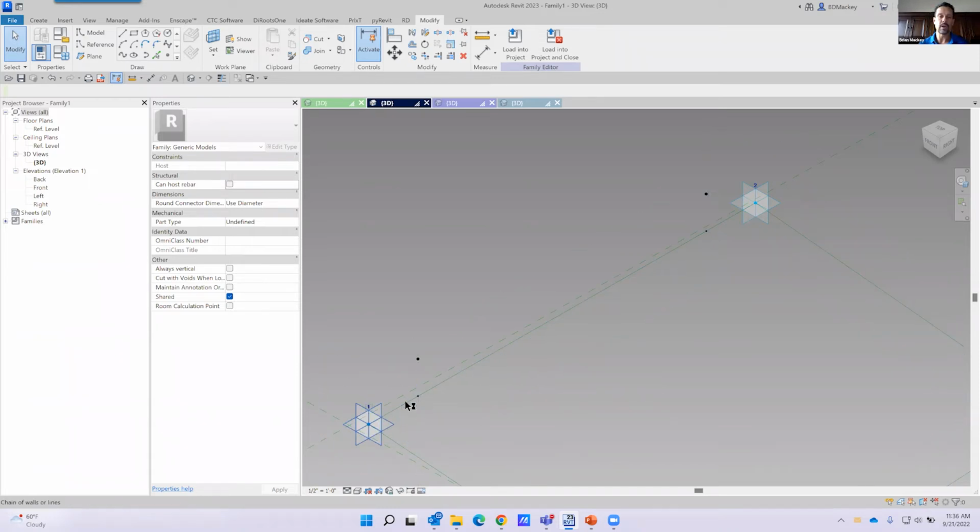A lot of times people would just be like, oh, I'm going to put a profile on here and host that profile and move that profile off. Again, every time I've tried to do that, I start getting weird scenarios. The best example I had is I had a client, they just had a 2-point adaptive and they hosted a rectangle. They drew a rectangle profile on this end. And then they said, sweep it along this path. And then as they were in the project environment, their little rectangles kept rotating and twisting. So they were trying to make a 4x4 wood sculpture with all these 4x4s of different lengths, and they all kept twisting on them. By hosting a point on here and then putting a profile on that point surface, it stopped the twist. So yeah, this becomes a good thing.